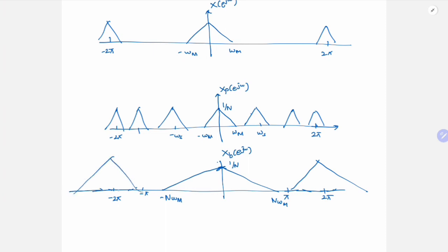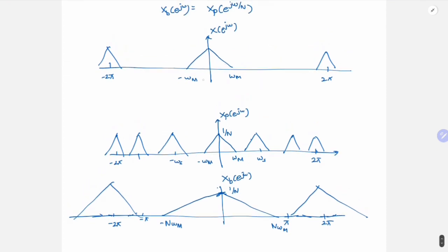So this one is not to scale, but this is the overall picture. So what is happening? This was our original signal. If we had just sampled directly at 2 omega m, we would have directly got something very close to this. This pi will exactly coincide. But since we sampled at a higher frequency rate, we were getting many more replicas inside minus pi to pi, right?